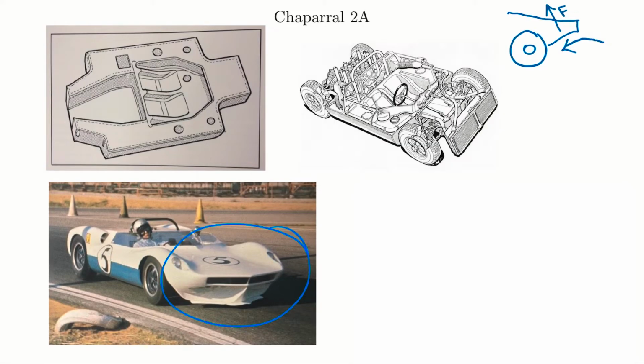As they were testing the vehicle, and remember they have their own racetrack here, they figured out that there was too much lift at the front. So they put an air dam on it, and I'll show pictures here as well so you can see this. I'm showing here when the airflow is redirected upwards, the air dam actually had to push that air up and over. So the force that the air pushes on the air dam, equal and opposite, pushes down and backwards, right?